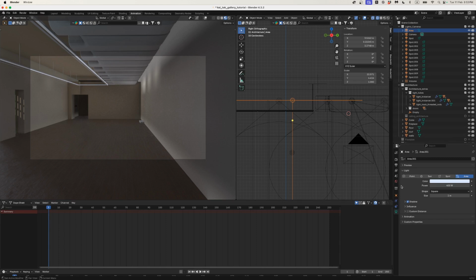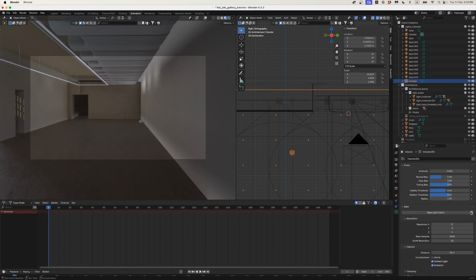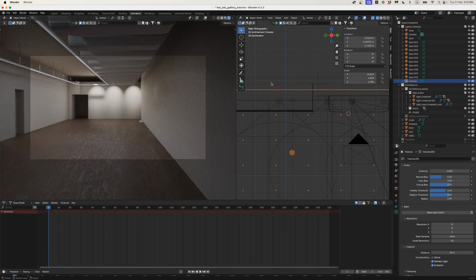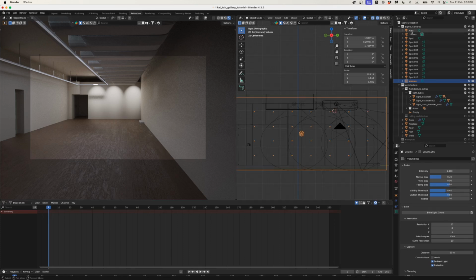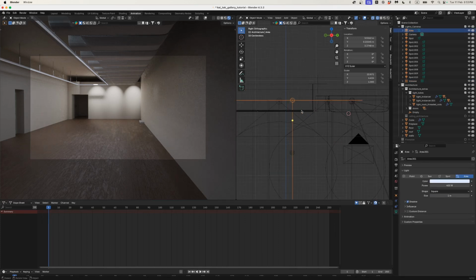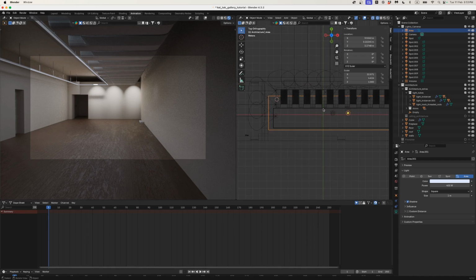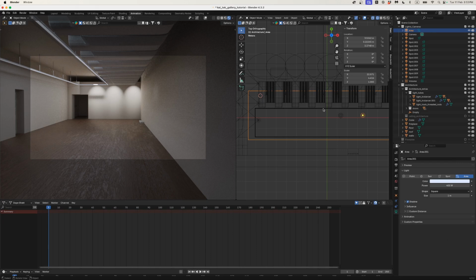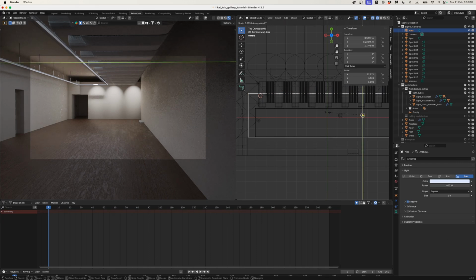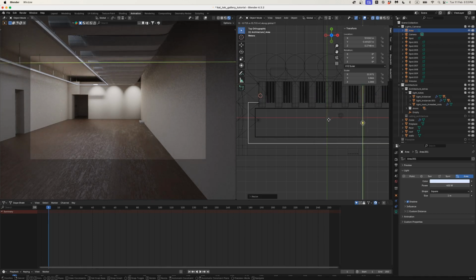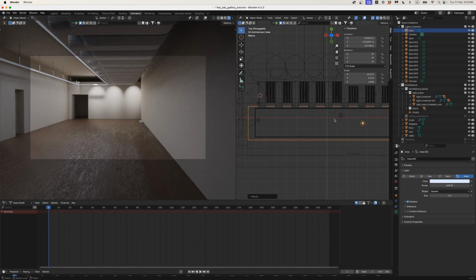So actually, I'm just going to quickly go into my volume here, delete my lighting cache, make sure I'm in rendered mode here, and I want to make sure that area light is not stuck inside something. And I want to make sure it's on top of where the, oh yeah, because I moved my lights. So let's just scale on the y-axis. G, Y. Yeah, because we can't have lights coming from behind the air conditioning system. That would make no sense.